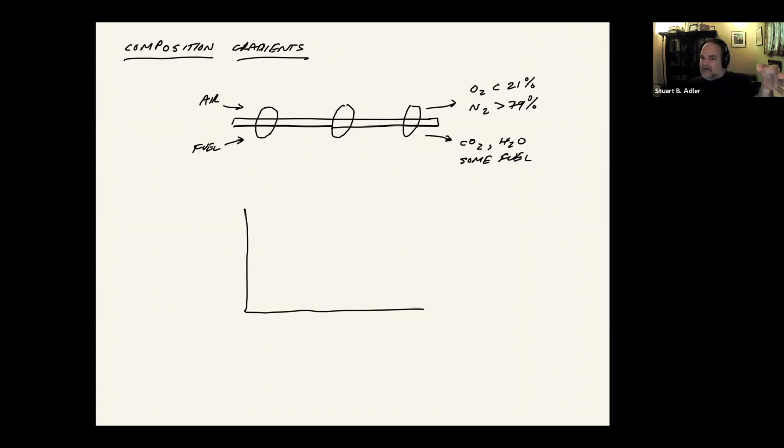We stick it into a test rig, put air and fuel gases over it, and measure the polarization curve, fixing the gas concentration. There's no utilization in the cell test, just gases at a known concentration, so we can calculate the Nernst potential and characterize the overpotentials. All these things we can measure as a function of gas concentration or temperature, and you get a polarization curve.